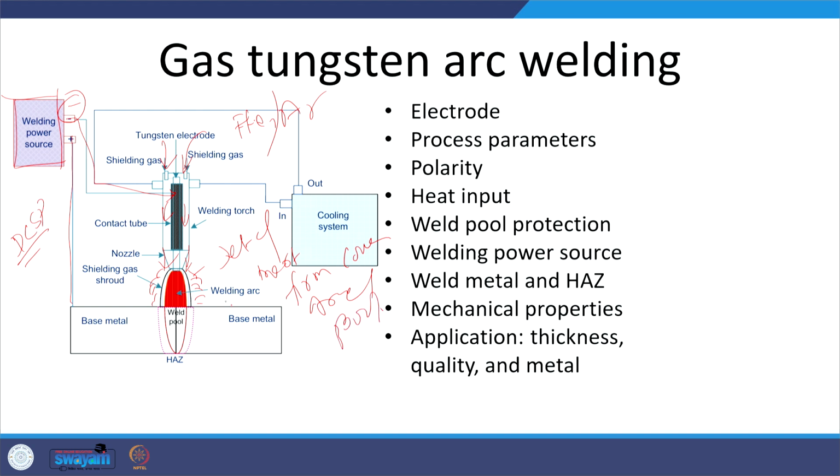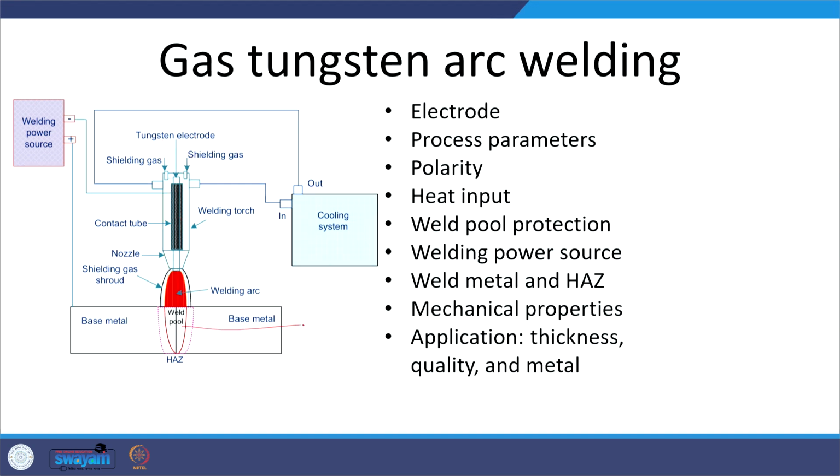When this firm cover of inert gas is formed, it provides effective protection to the weld pool. So, the protection of the weld pool in GTAW is really good, and therefore we get a very reduced percentage of oxygen and nitrogen in the weld pool, and that in turn helps in producing the cleanest weld metal by the GTAW process amongst the arc welding processes.